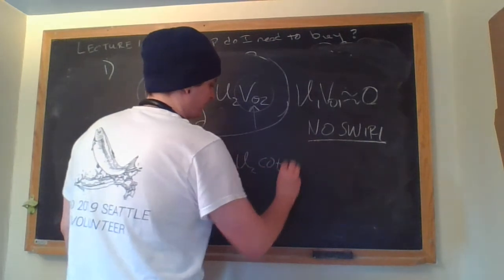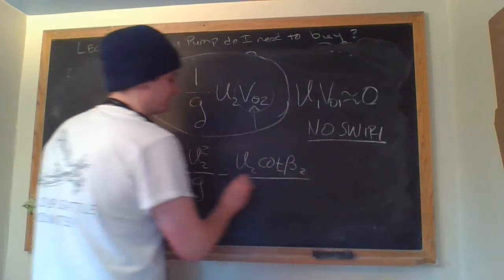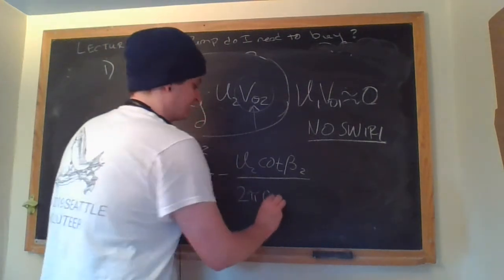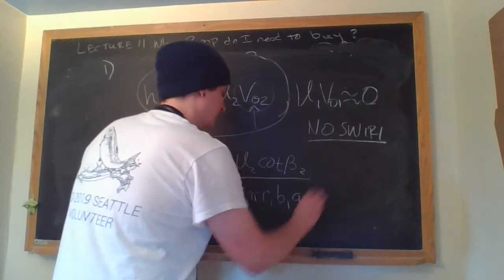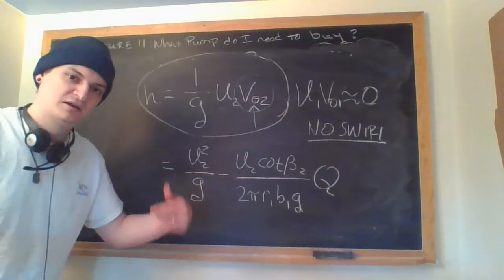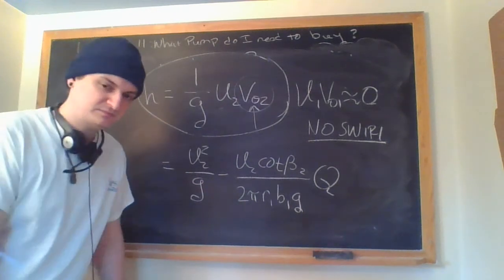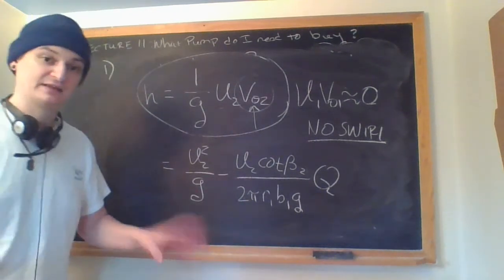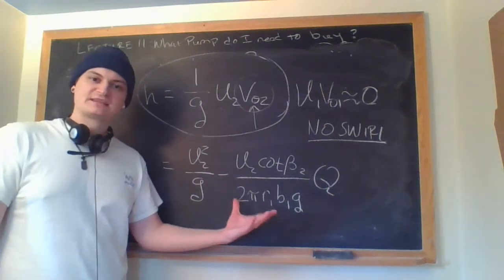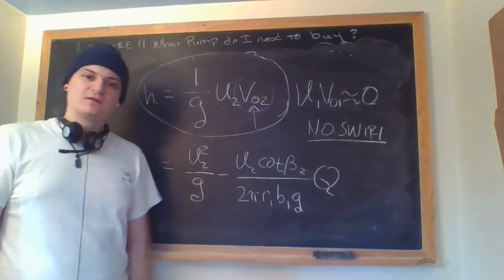The ideal pump curve, in terms of parameters that you can design, that you can estimate in a first stage of design, is a linear approximation to your flow rate equation and a linear approximation to your head loss equation. Remember I said you could always estimate what it is by any given polynomial.